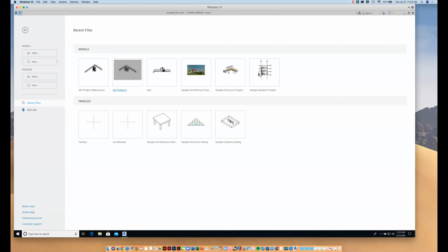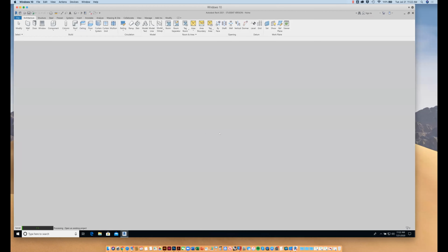Okay, finally, Revit opens up. I'm just going to open up a new file. This is what my splash screen looks like when I first open up Revit. I'm going to say new model, just create a new Revit model from scratch. Imperial construction template, that looks good. Imperial meaning feet and inches rather than metric. Maybe I'll say architectural template, I'm not sure. But if it says imperial, then you're going to be dealing with feet and inches. And I'll let it just do its thing.